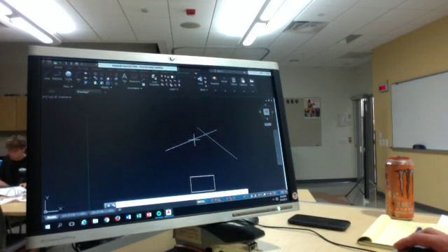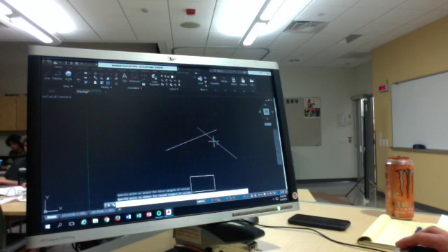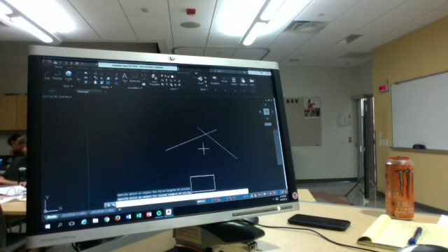So you can take one of these, and then for the radius, let's just say it's 7. Tangent, tangent, radius. So it's tangent to this point. That line is parallel to the outer part of the circle right there. Tangent to this point, and its radius is 7. You'd be shocked by how often I use that.